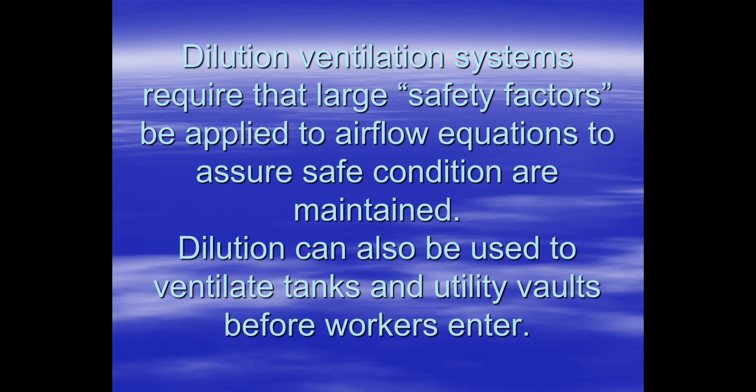Okay. And also I need to make sure I'm monitoring for production of other materials, a lack of oxygen, and other things. But by blowing that air through and diluting the air that's in those vaults and controlled spaces before my workers enter, I can reduce the overall risk that that atmosphere presents to my workers. I probably want to make sure that those workers still have proper respiratory protection, based on what I think potentially they could be exposed to, but it makes it safer to take some of those IDLH situations or fire and explosion situations away before my workers enter.